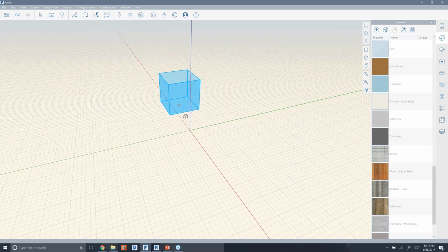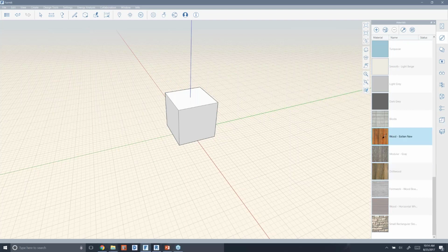So what I'll hit on quickly for those who are new is how materials work in FormIt. You see the little preview over here, so you can see if it's a textured material or if it's just the color. I'll click the thumbnail preview to enter the paintbrush tool and then single click on the face, and it's going to paint just that face. If I click on the preview over here in the panel again, and then double click on the cube, it's going to paint the entire object. So every face now is painted with that material, and it overrides the material that was there before.